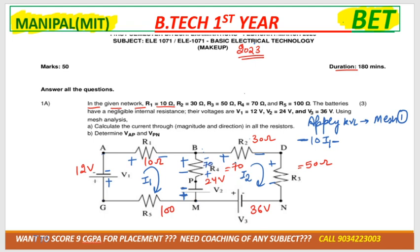That is 70, they have given. So it would be minus 70 (I1 minus I2). If you are taking the first mesh, it is I1 minus I2. If you take the I2 mesh, it is I2 minus I1. Correct? Then the next sign, plus 24 minus 100 I1 minus 24 is equal to 0.